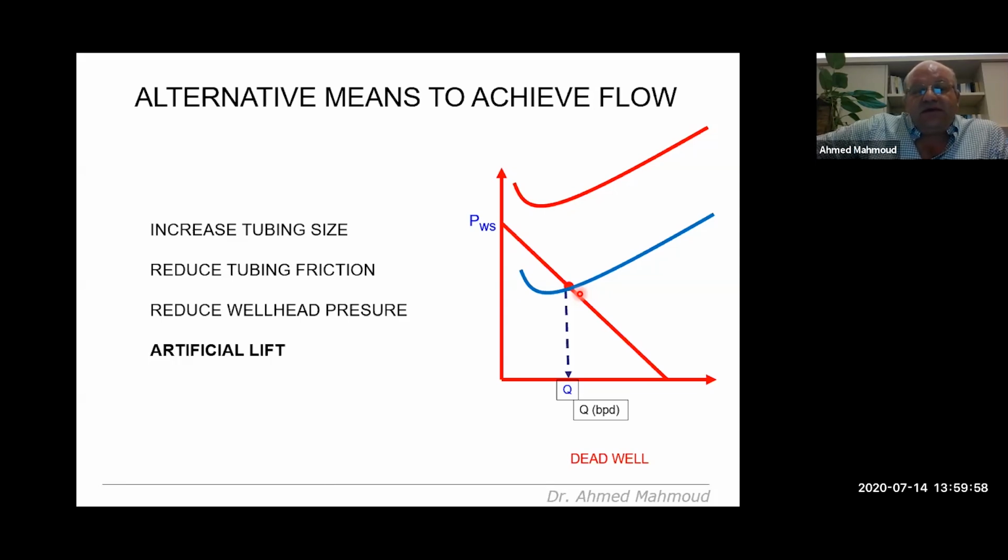And what will dictate that more is because depending on the rate you are injecting your gas and the pressure you are injecting your gas, it will automatically dictate the rate at which you are reducing the hydrostatic pressure inside the tubing. And it is this delta P, okay, that will be time related.